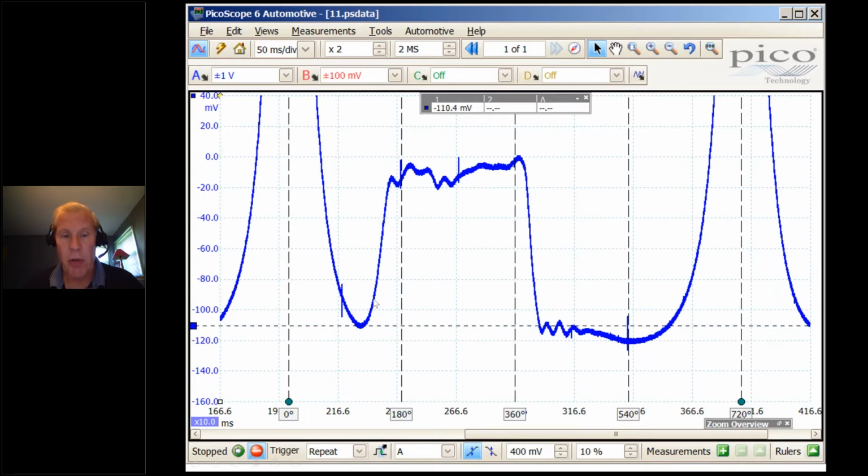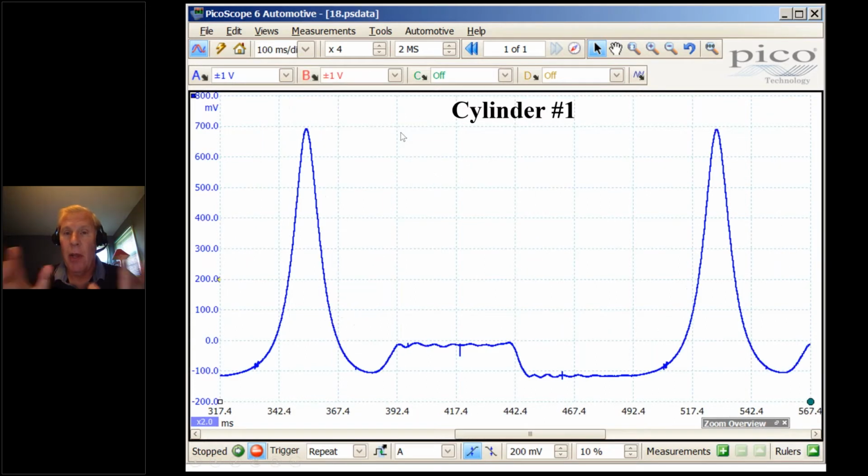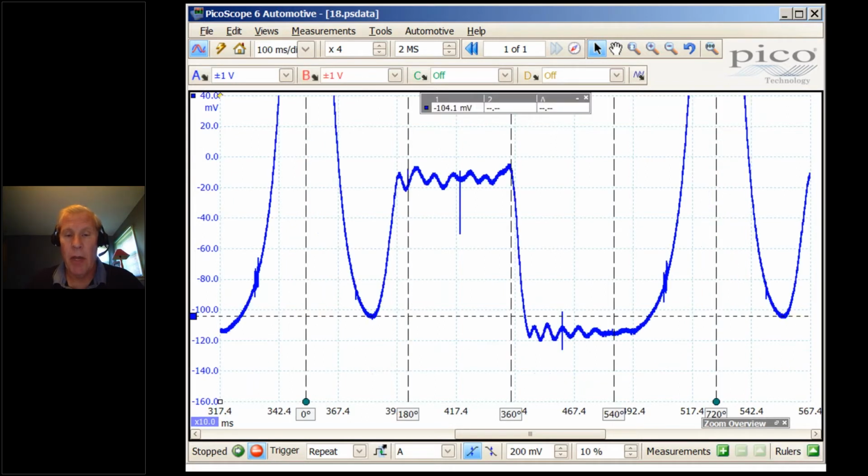So that's about 22 inches, and that's pulling about 24 inches. So it's not as bad as that Corvette example a moment ago, but something is there. Something subtle is going on there. Here's a good cylinder for comparison. And you can kind of tell right away that as I zoom in, there's a difference in depth, which again, Hemis have pretty aggressive cam timing, but